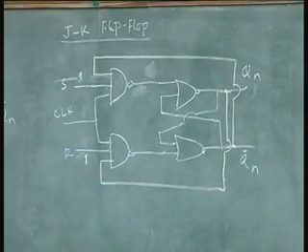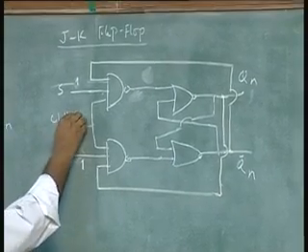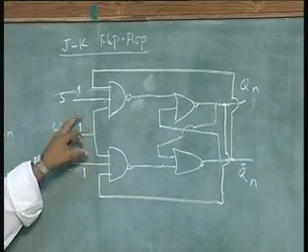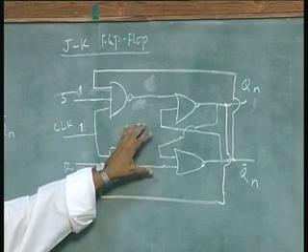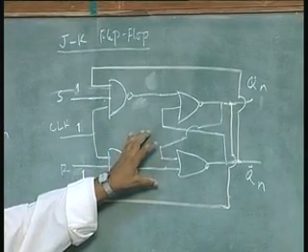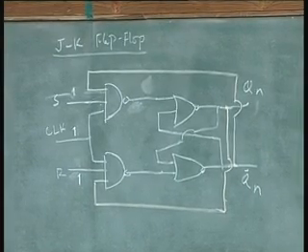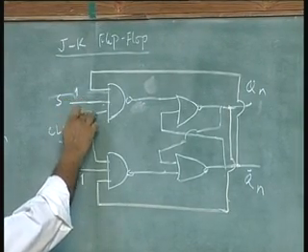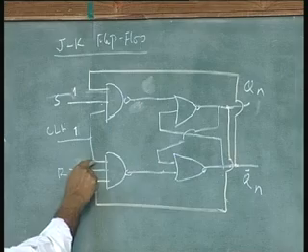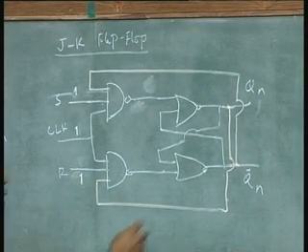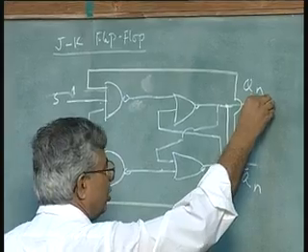Of course, we will analyze the circuit when the clock is 1, because when the clock is 0, the flip flop's input is not going to be effective. In this sense, the flip flop is going to store whatever value was put in it before the clock became 0. So we are going to analyze the condition 1 1 for these inputs. Let us assume an output condition of 1, because we have to start somewhere,